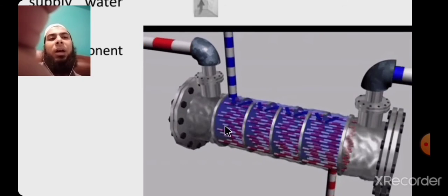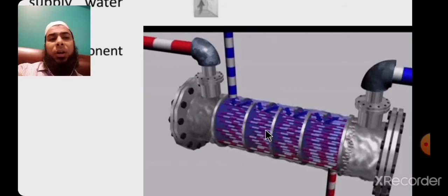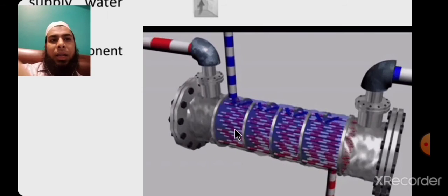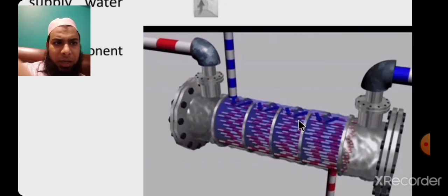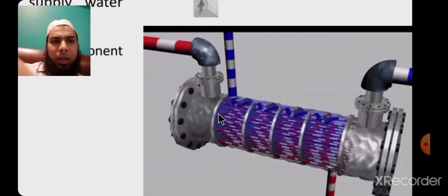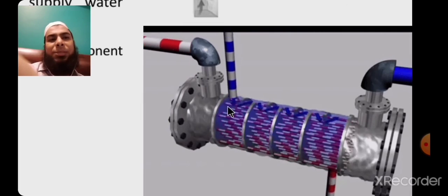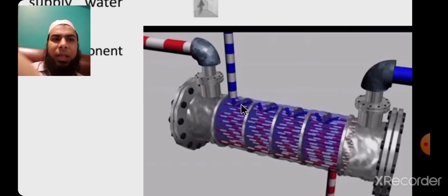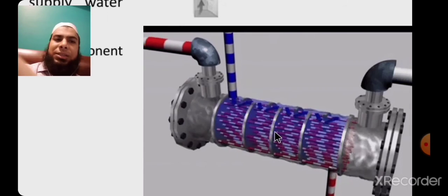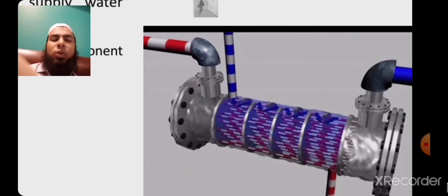Similarly, this kind of shell and tube heat exchanger is used to cool down the water with the refrigerant. On the shell side we have the refrigerant, and the refrigerant cools down the tubes. You can see that it is a long copper tube, and there are a lot of tubes connected here. So water comes in the copper tube, and the surrounding space is filled by the refrigerant. The refrigerant basically cools down the water and does not mix with it. It just transfers the heat. It itself changes its phase from liquid refrigerant to gas, and that gas goes to the compressor, and the circuit continues.